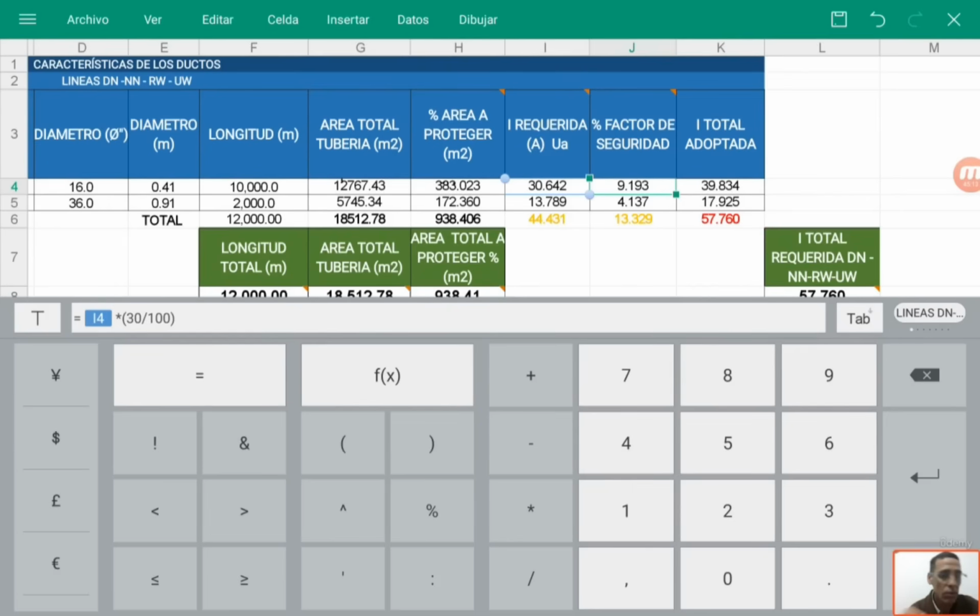Don't just look at things based on the conditions, unless you were the quality assurance inspectors during the pipeline construction phase, and you made sure that the coating was in perfect condition, that a holiday detector was used, that everything was flawless, and you can guarantee, no, look, I only considered 1% because I'm sure the pipe is fine. If that's the case, then you can assume the 1%. If you're not sure, don't. And you know how construction processes go when the supervisors aren't around, when the owners aren't there, when you notice the contractors looking the other way, they didn't put a heat shrink sleeve on the joint, and now you've got corrosion problems.